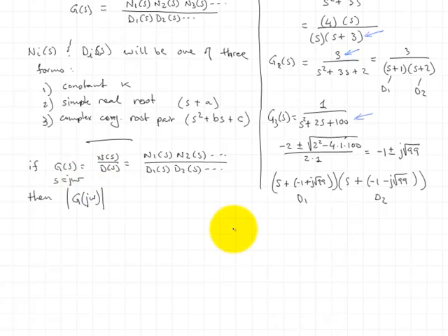In other words, a cosine omega t, for instance, according to Euler's formula, is decomposed as e to the j omega t plus e to the minus j omega t, all divided by 2. So we're using terms of the form e to the st, that is the excitation, and that's where the s comes in when we write our transfer function. But when we restrict ourselves to exciting the system with sinusoidal signals, we are restricting the values of s to